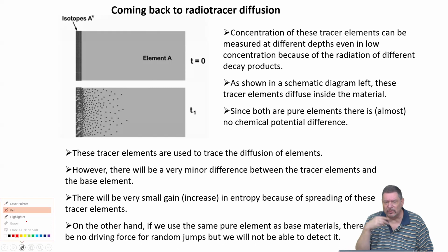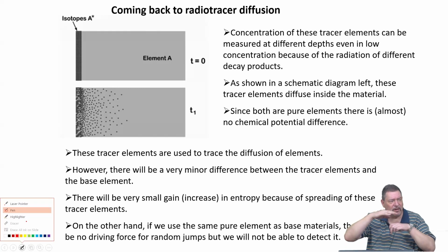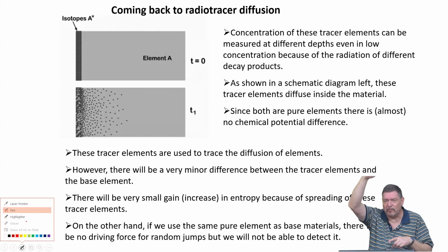So even if you go to TEM, even if you go to AFM, STM or so, you will not see individual atoms jumping. That's because of the aberrations all the methods have, and also especially in TEM, you always have a projection view. So even if you make a very thin foil, you will basically collect the information on a 2D detector that contains all the information of the interaction of the electron wave, which you use incidentally, through the thickness of the foil.